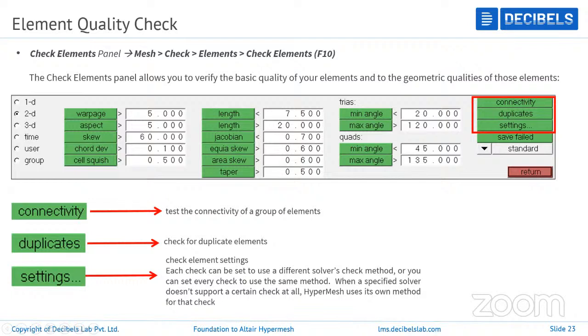The idea of using a quality parameter is that throughout the component, we are unable to keep the perfect shape of the elements. To match the CAD, we are deviating from the ideal or perfect shape, but the deviated element should be within this defined range only. So how the quality parameters are implemented, we'll see in HyperMesh.